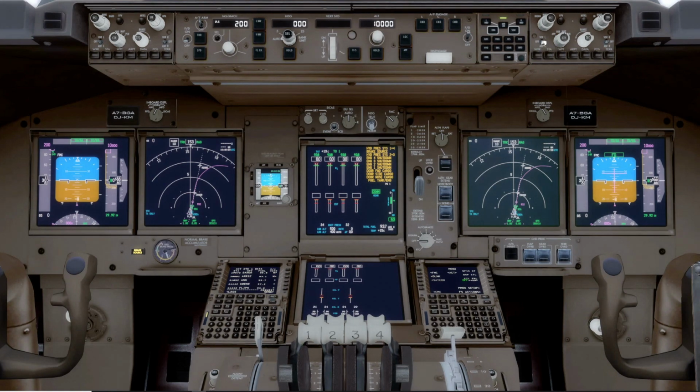EFIS control panel, we could go to VOR, or we go to ADF and VOR just to make sure that ADF's blue, it's working, and VOR is green, it's working. And then you could go to VOR for both when you're done with that. And as a technique, you maybe want the airport switch on for display airports after you take off. And then the radio baro would be negative, so it's not displayed.